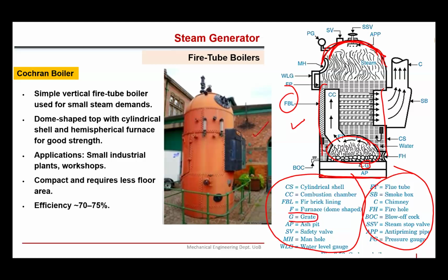Now, what is a grate? A grate is a kind of platform in the furnace upon which the fuel is burned, and it is normally made up of cast iron bars, right? These bars are arranged so that air may pass to the fuel for combustion. The area of the grate on which the fire is resting in a coal or wood-fired boiler is called the grate surface, right?